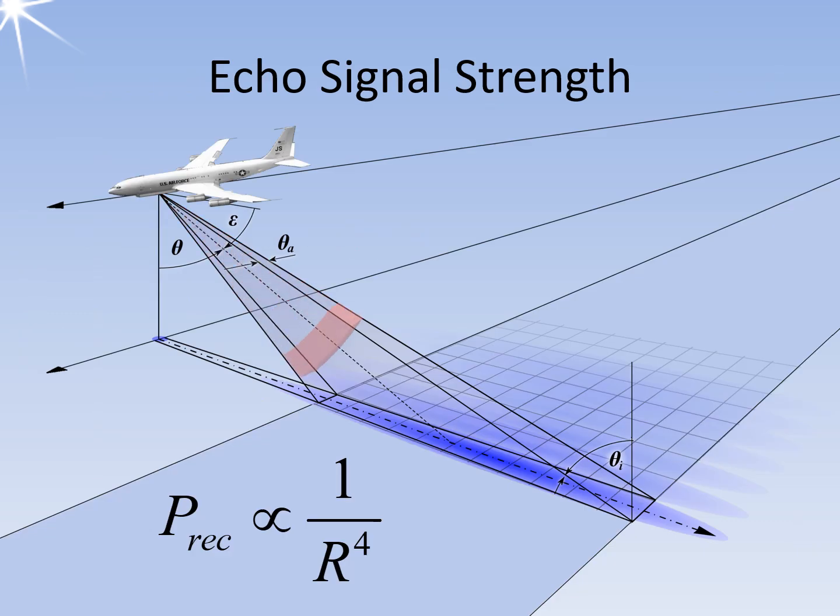The range resolution deteriorates at the near swath, the angular resolution at the far swath. The mean distance of the image strip should be selected from these two values to ensure that the single pixels are approximately square. In this example, that would be approximately 5.5 kilometers.